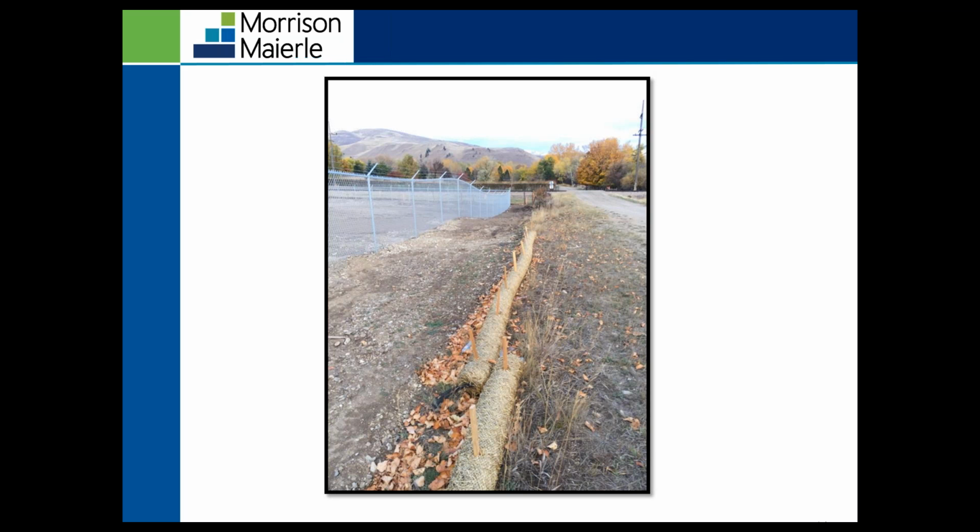I see this when I'm doing my inspections for this permit, that it's not trenched. You want to make sure that this BMP is trenched into disturbed soils. If it's not trenched, stormwater can undermine it, allowing stormwater and sediment to discharge from your site. Also important to know is that this BMP does not allow water to flow through it. It creates ponding as well.